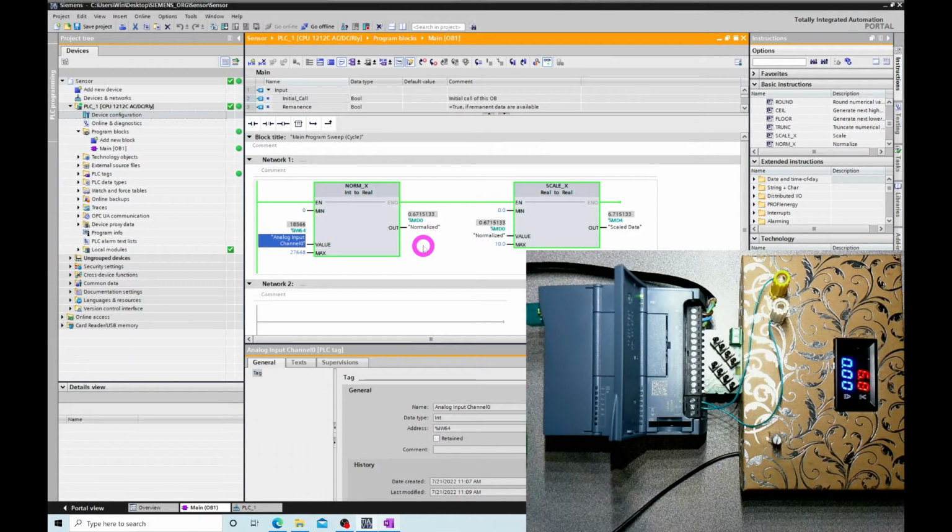Again, you need to save that somewhere in internal memory. That's the reason I use %MD0. We already talked about this in internal addressing in the previous video, so please watch it if you didn't. With %MD0, we reserve a memory location whose length is a double word, which means 32 bits. You select the biggest one so that you don't lose any of the data, and save it in this place in your memory.